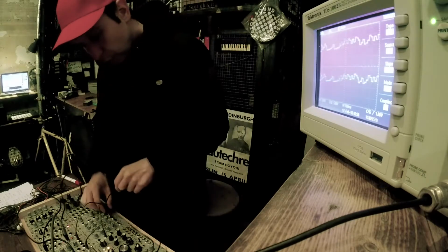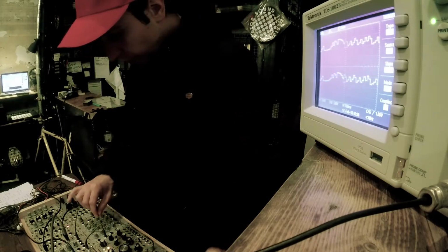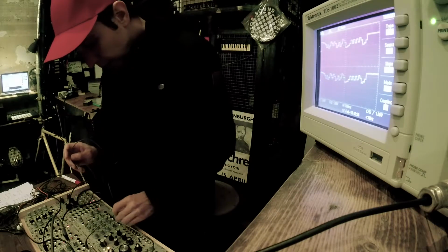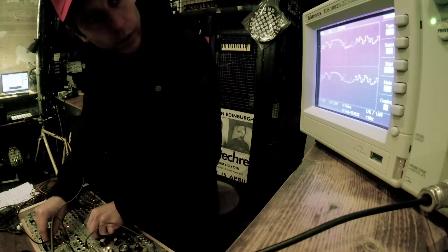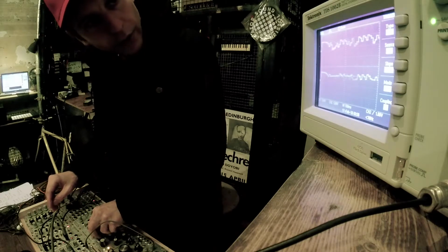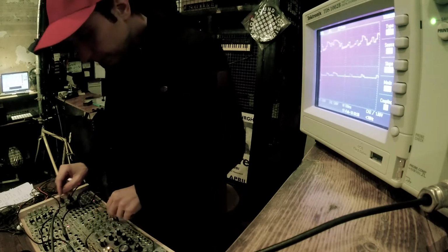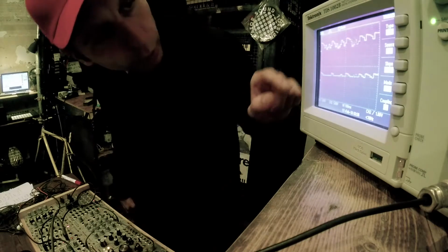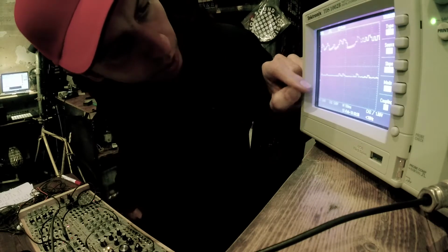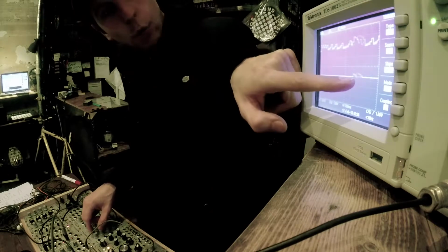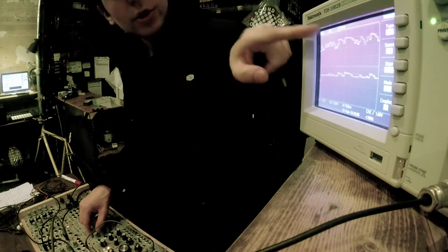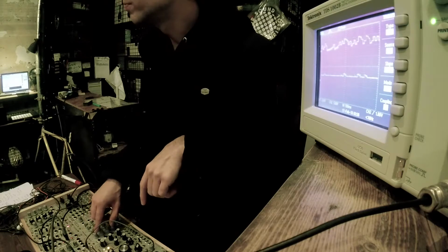So in order to cap it from below, what I need to do is put a DC signal into one of the inputs. You see, and now if I increase this DC signal, I'm probably somewhere above, well, I can probably even read it. Now I'm at almost 5 volts. You see, now I get only the bits that come above 5 volts.